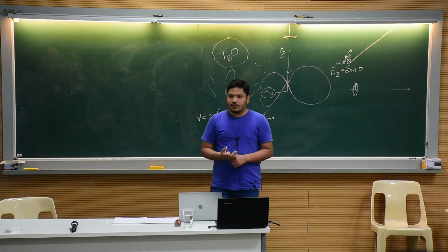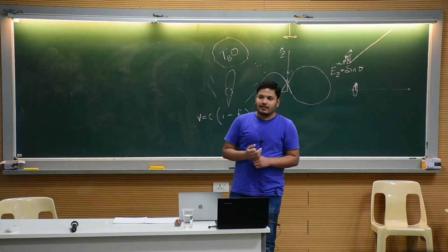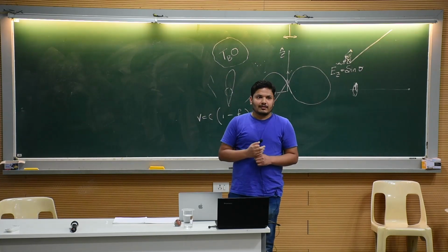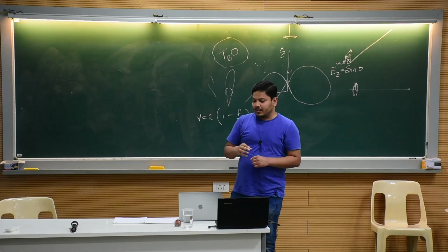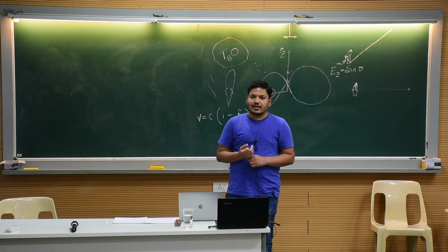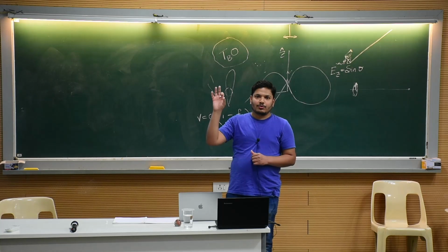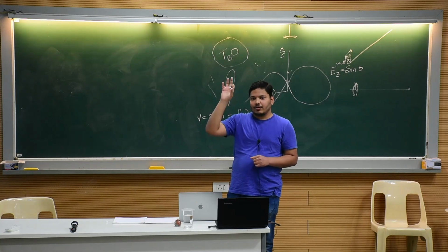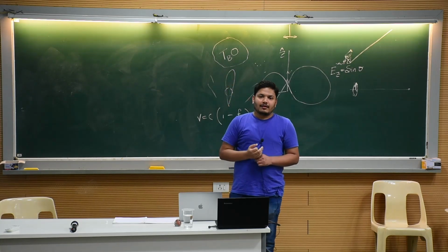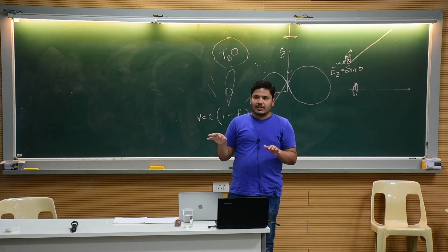We'll use what is called the y-factor method or on-off method. You need two extra observations for this correction. You point it to some blank portion of the sky or just near the zenith. That should give you one temperature reading.